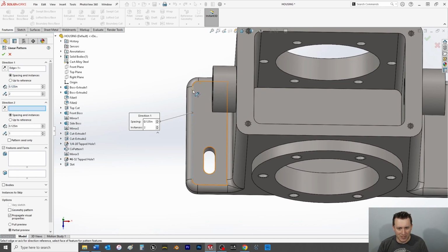Now notice something, the direction arrow is pointing down. In other words, if we were to select this slot right now, it's going to make it off that flange feature. So we need to fix that. Simply change the direction by coming out into the properties and reverse the direction here. And now we're on page 97, section 2.61 for this next part.